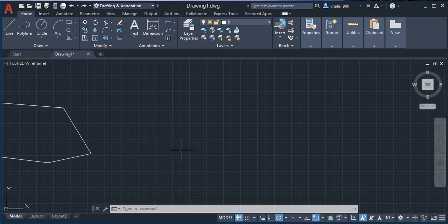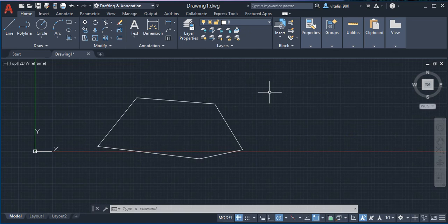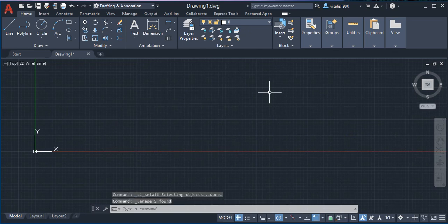Okay, so using specific coordinates. Before we go into that, you need to understand that, by default, AutoCAD uses absolute referencing only and only when the dynamic input is off. If the dynamic input is on, AutoCAD uses relative referencing as default.